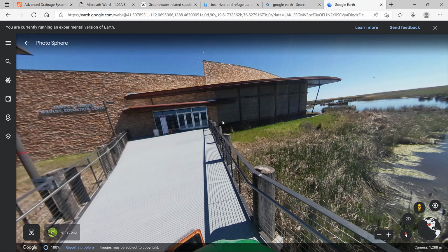If water got into the basement, the sloped floor went to all these individual sumps, and they were fine with having a little bit of water on the floor, and it goes to like these 20 or so different sumps around the building, just little 1 foot depressed areas, so they can put sumps in there, and they're on a float, and piping that's piping it, so that this building has a bunch of little pumps all around.